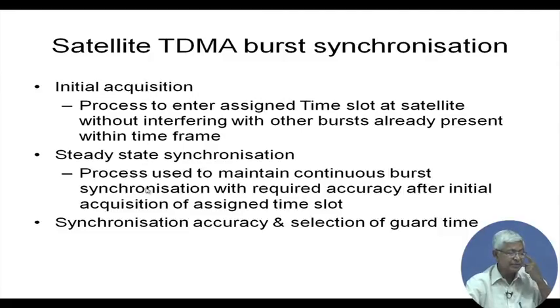And steady state synchronization is, once you acquire your slot properly and you know when to transmit, the process used to maintain the burst synchronization continuously with the required accuracy is called steady state synchronization.